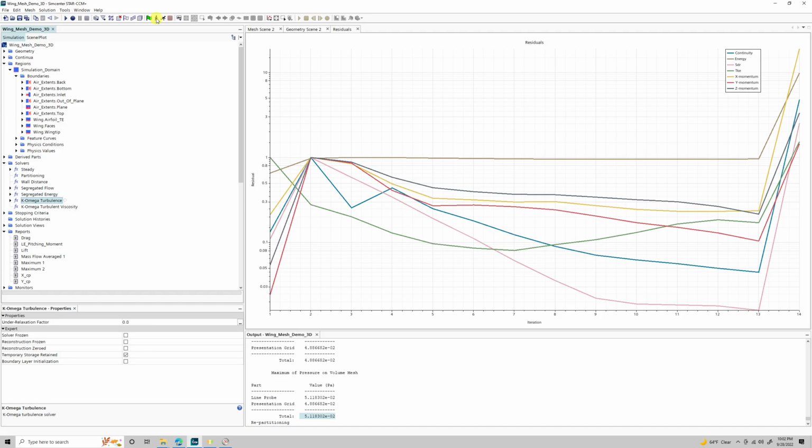I remeshed and made it polyhedral, so all the cells change not just how big they are, they change shape and everything. Because all these values changed quite suddenly, the residuals jumped quite a lot. What's left over in those equations when it's calculating them got quite large.